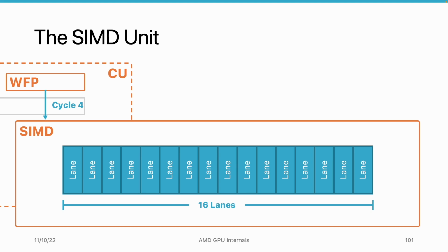And there is typically a ratio between half precision computing and single precision computing capability. In older GPUs, it's 1:1, so 16 lanes for half precision and 16 lanes for single precision. In newer GPUs, it's a 1:2 ratio. That means for 16 lanes of single precision, there are 32 lanes for half precision. Moreover, we also have double precision calculation, and the ratio between double precision computing capability and single precision computing capability varies from GPU to GPU.